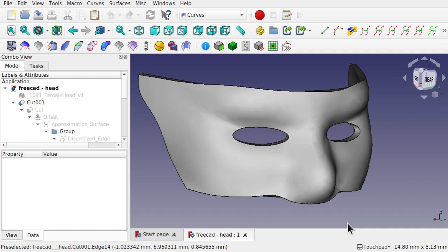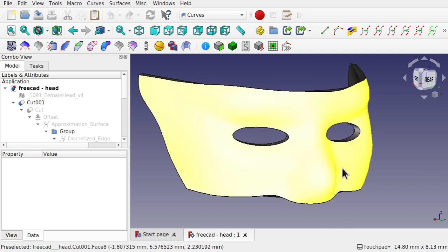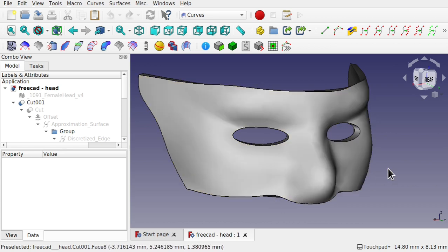So our first one, I'm going to show you how I created something like this. I think you're going to like this one because it's quite quick to use this tool and you can get instant results from it. So in this video we're showing two techniques. The first technique is to take two curves, discretize them and create a curve between those to create another surface. And then we'll move on to creating a mask like this. So this is created from profiles, placed into a group, and we use that group to create the surface.